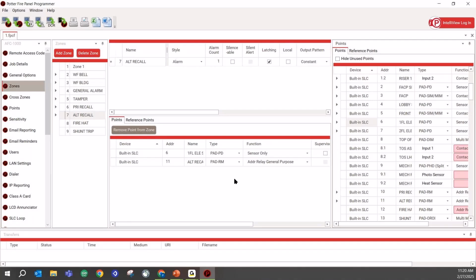So, to that point, when do we take elevators out of service? Well, we take elevators out of service because smoke has been indicated in the elevator lobby of one of the floors. So the point there being is we no longer have a tenable evacuation route in that elevator. So we want to go ahead and take it out of service at that point.